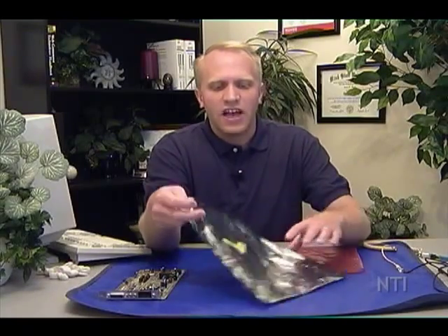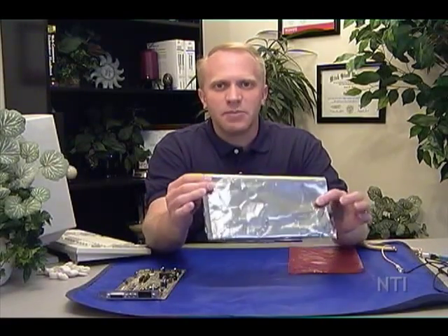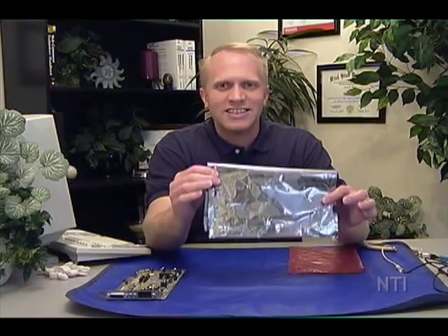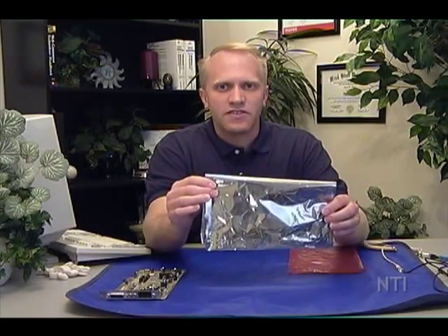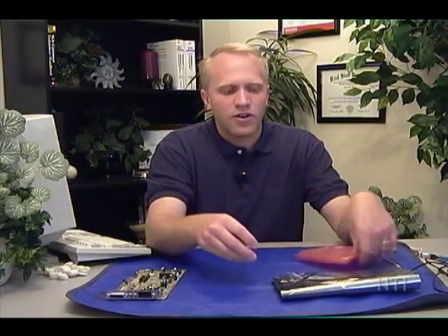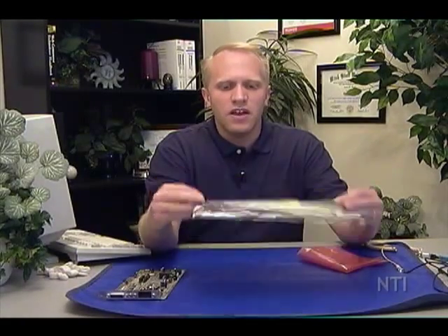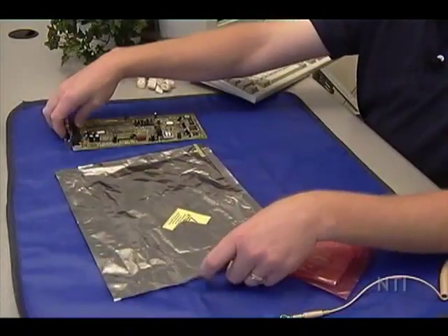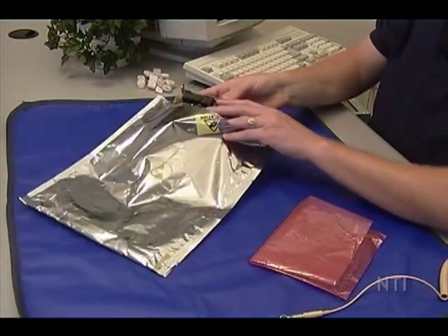Now, it's important to note that there are many different types of static bags. This one that I have here that has the silvery tint to it is the best you can get. This is called a static shielding bag. This will protect a component on the inside really well. There are other types of static bags, however. Sometimes you'll see a pink one such as this, or maybe a blue one. These are called anti-static bags. Now they will work, but they don't work as well. They act more as an insulator rather than a dissipator. They will work, they will protect your components to an extent. However, I strongly recommend that you keep your components in a Mylar type bag that looks like this with the silver coating on it.